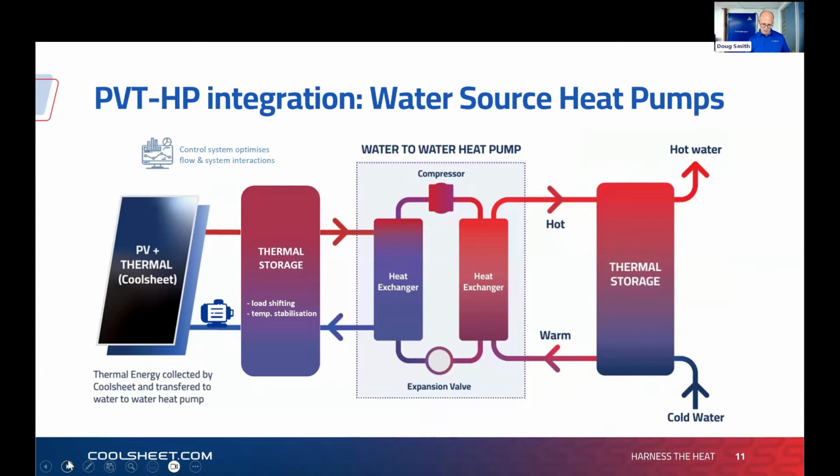Water sourced heat pumps, we think that's going to be an interesting driver for our business, for PVT in the world. Water sourced or hybrid. A number of things really to say there. The Coolsheet system, unless you've got a swimming pool where you're cycling the swimming pool water directly through the Coolsheet, it's rated to run salt water or chlorinated water. But generally, I think you get a more effective and faster ROI by twinning with a water source or hybrid heat pump.